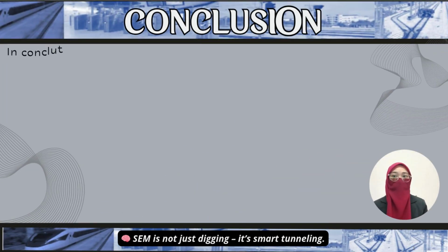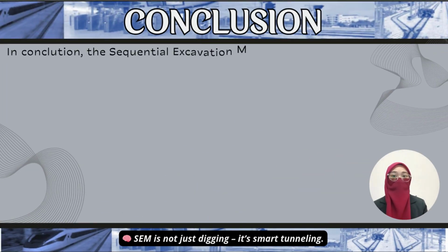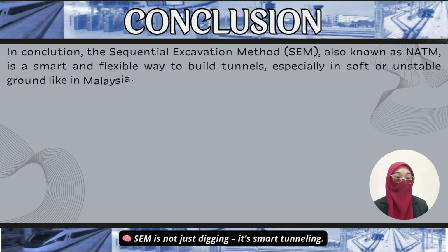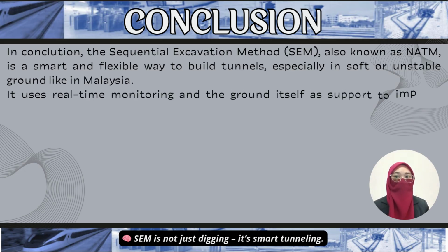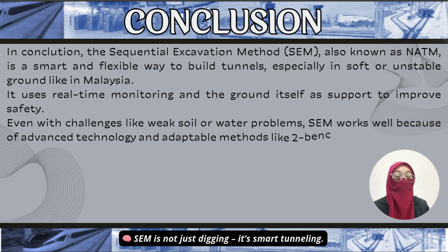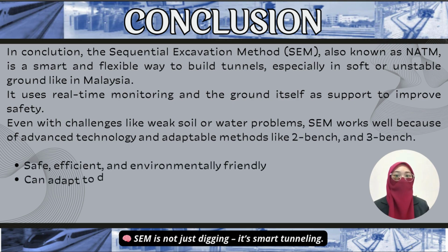In conclusion, I believe the sequential excavation method, or as we also know it, NATM, is a smart and flexible approach to tunnel construction, especially in soft or unstable ground like we have in Malaysia. It utilizes real-time monitoring and the ground itself for support, which significantly enhances safety. Despite challenges such as soil or water issues, SEM remains effective due to its advanced technology and adaptable methods